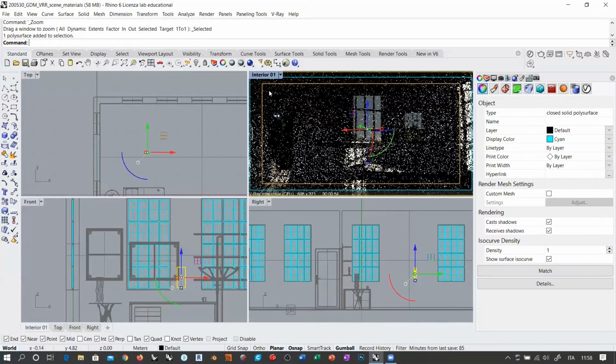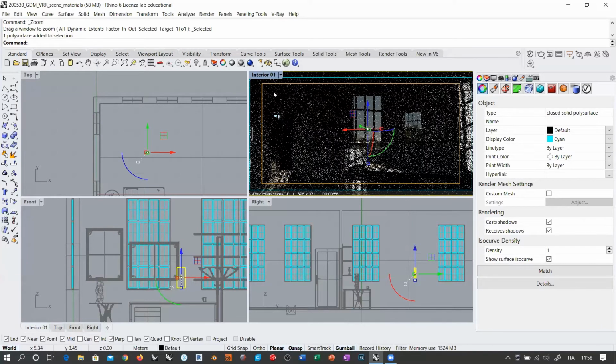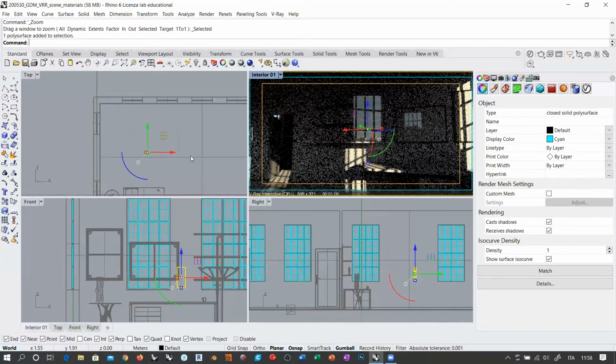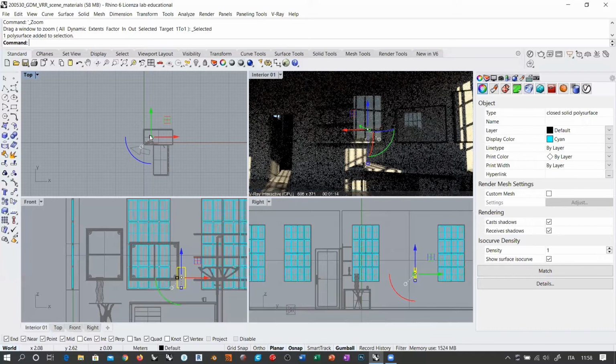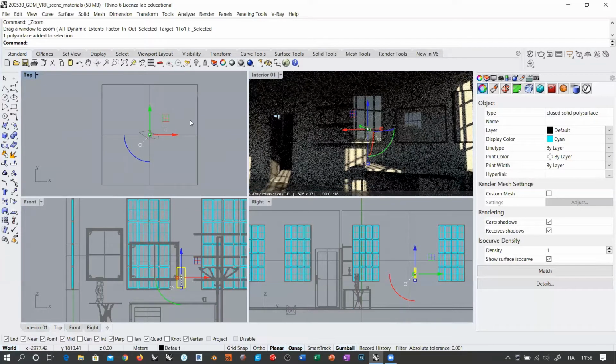This is due to, well, it's basically the graphic card, actually. And this happens because my scene is too wide. So this small detail cannot be rendered by the graphic card because the graphic card is occupied in rendering all this thing here, which is the one thing that I placed also yesterday at night, which is the V-Ray infinite plane.